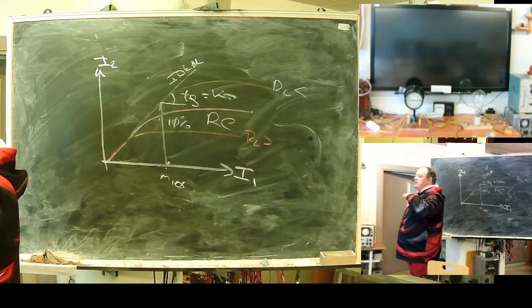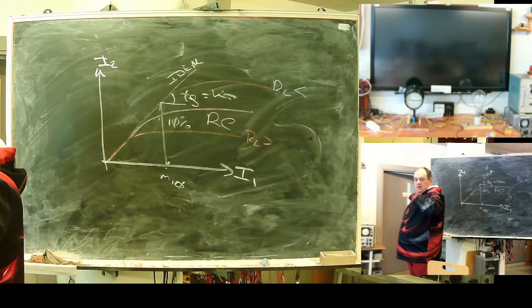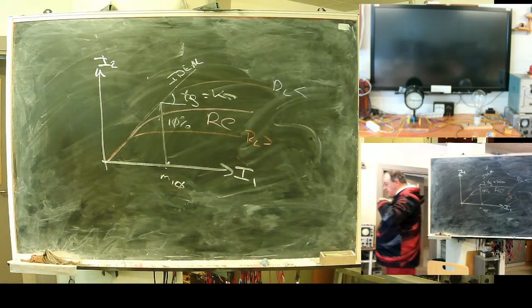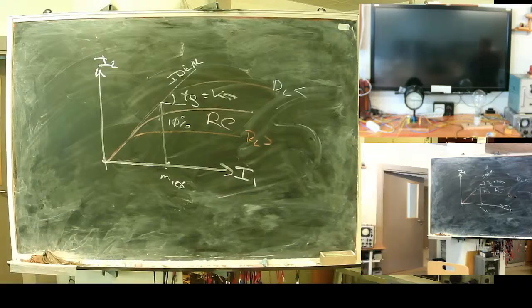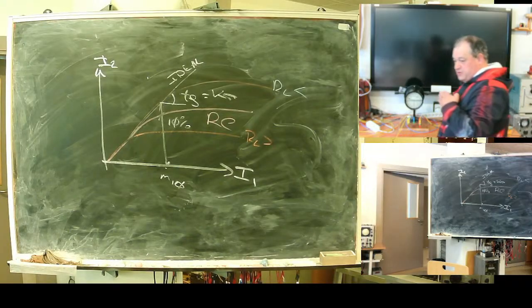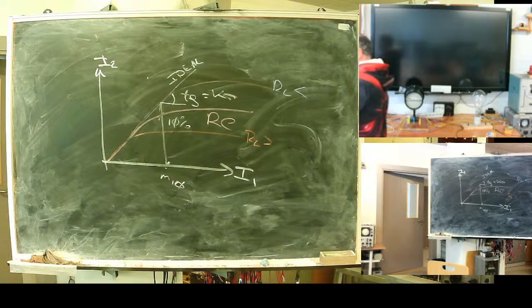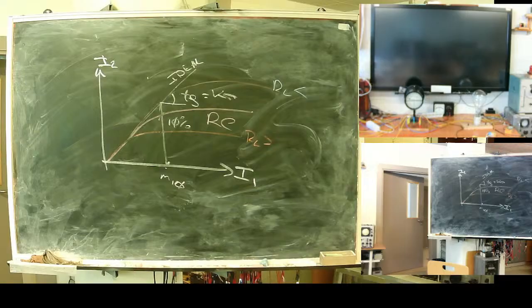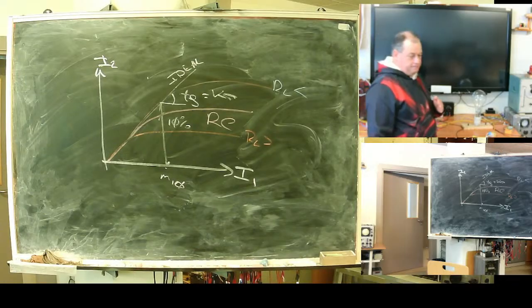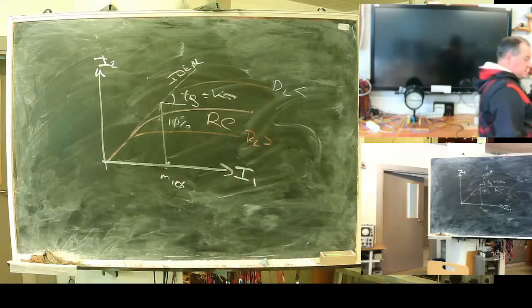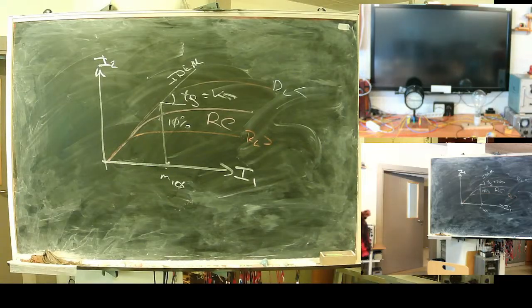So in reality, you should maintain a lower level of signal at the processing stage, not lower than 1 volt, something like this. The lower level of signal is determined by the signal to noise ratio, and this noise comes from your own power supply. It's not obvious, but it's a fact. Tiny spikes.